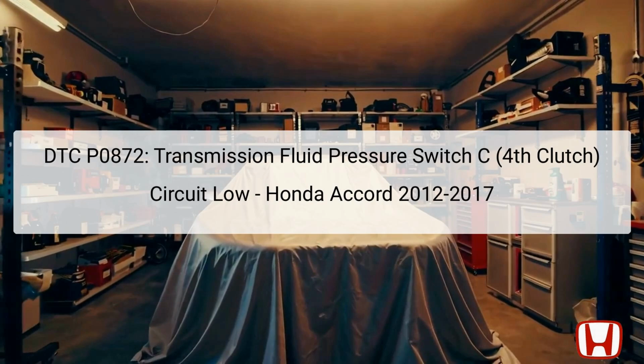The Diagnostic Trouble Code, DTC P0872, pertains to the transmission fluid pressure switch C, related to the fourth clutch in the Honda Accord models from 2012 to 2017. This issue occurs when the signal from the fluid pressure switch indicates a low status while the vehicle is in inappropriate gear ratios for the fourth clutch.